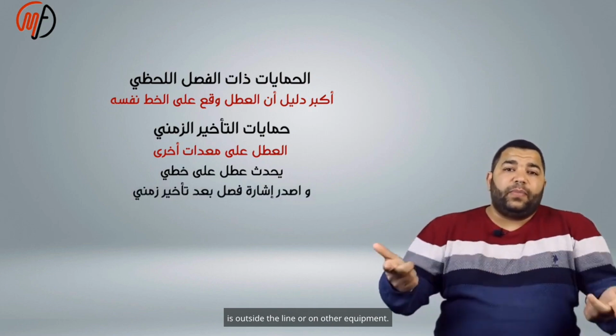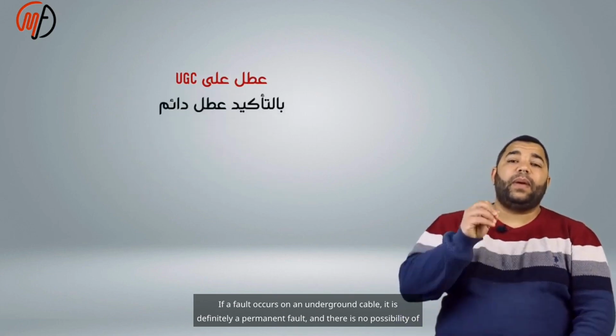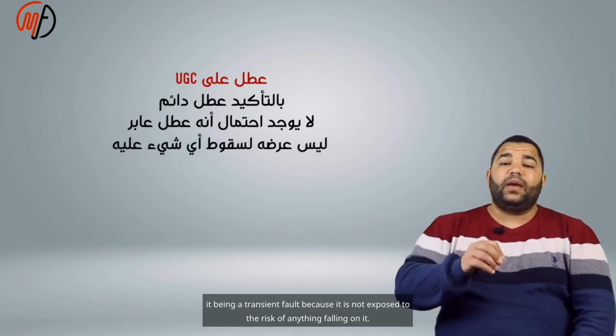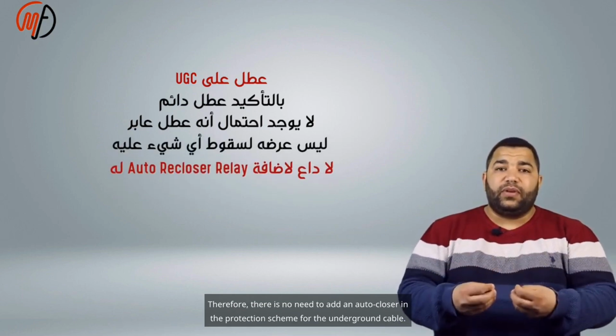If a fault occurs on an underground cable, it is definitely a permanent fault, and there is no possibility of it being a transient fault because it is not exposed to the risk of anything falling on it. Therefore, there is no need to add an autocloser in the protection scheme for the underground cable.